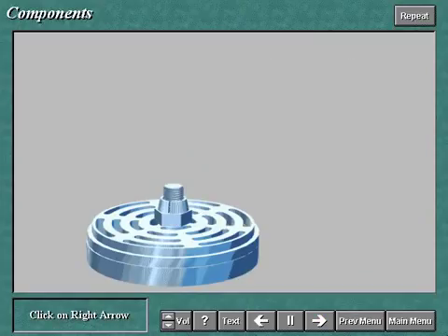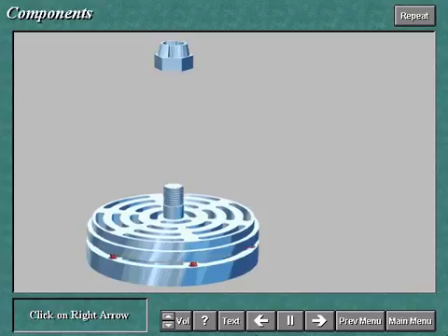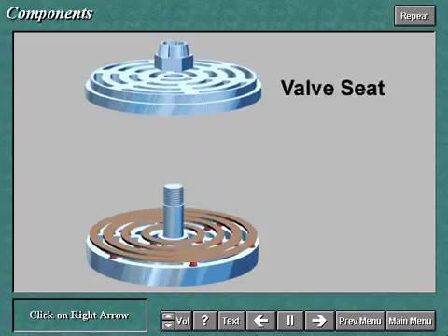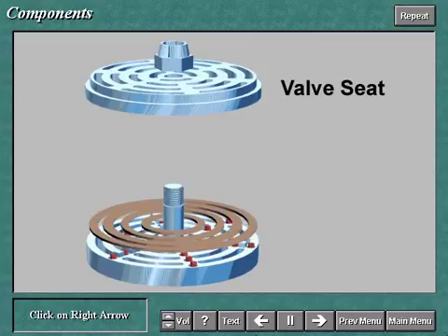All valves used on reciprocating compressors are made up of four basic elements: the valve seat, valve plate, springs, and valve stop. The valve seat is the circular component through which the flow ports are opened. It is sealed by the valve shutter. The seat and valve shutter together mechanically support the pressure differential. The seats are mounted in housings arranged along the body of the cylinder.